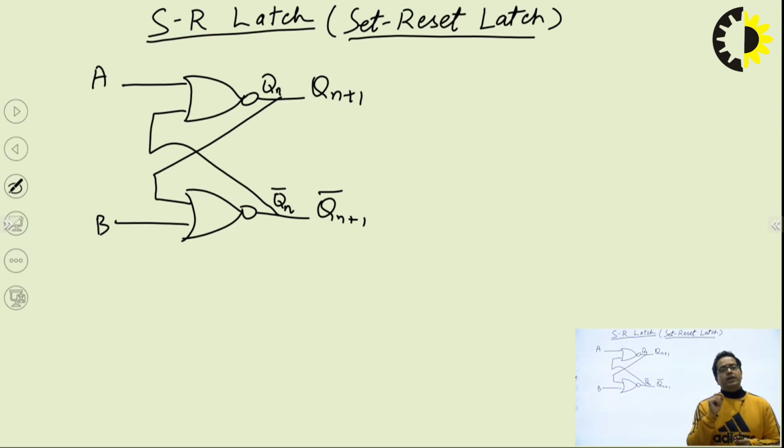I only know the value of the first terminal. Just try to relate this. Without knowing the value of the second terminal, what value should I consider so that I can predict the output of a NOR gate without even knowing the value of the other terminal? The concept is this one, right?